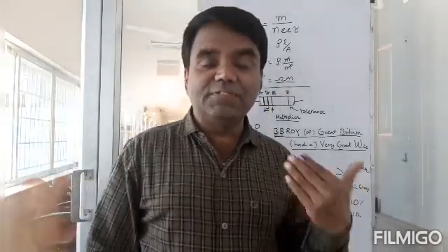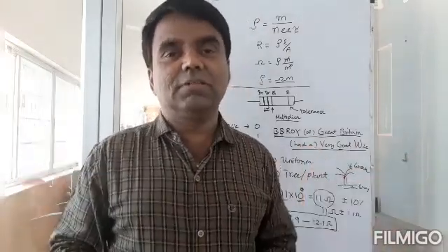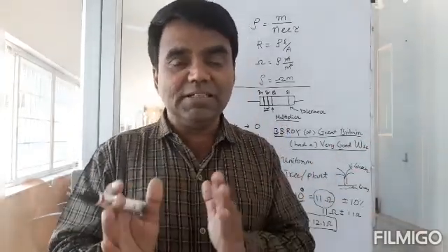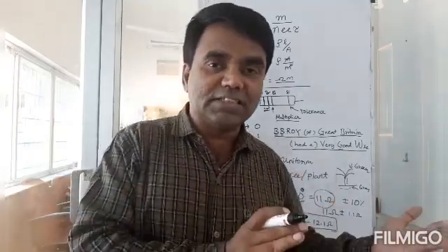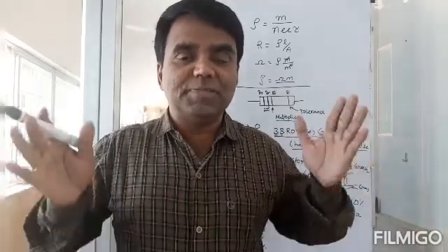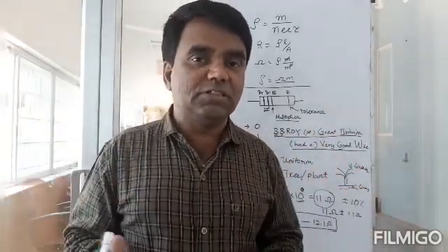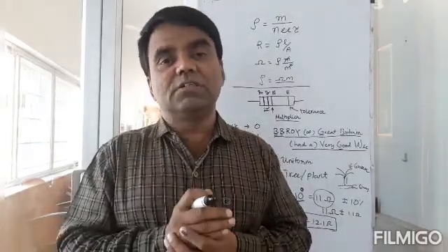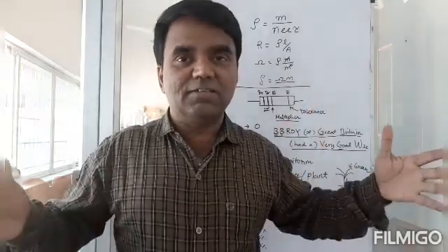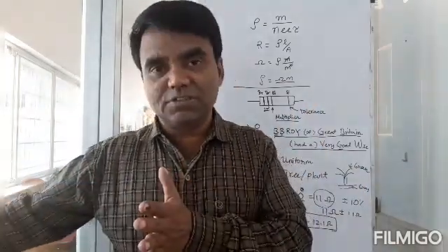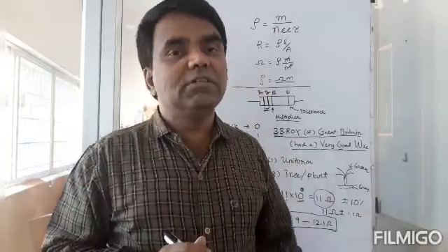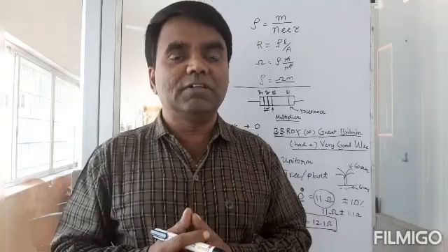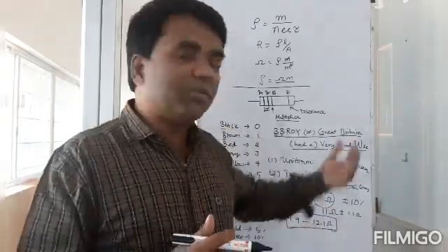This is the stated resistance. The manufacturer says that it is 11 ohms. That's what he says. But then he also says it is within 10% of tolerance. When I say it is 11 ohms, it can be 10% on the lower side or 10% on the higher side, or any value in between. The maximum variation is 10% on this side and 10% on the other side. But if I had used a golden ring, then it's only 5%, so better quality control. And if there is no line there, then it is 20%. It can vary 20% on this side and 20% on that side of this value, 11. So poorer quality control compared to the other two. I hope this is clear to you.